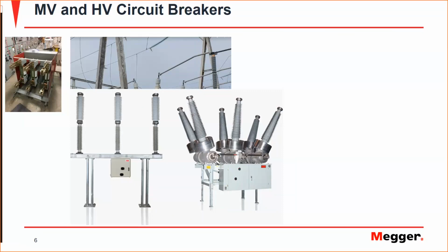The breaker on the left here is a live tank circuit breaker, where the interrupter section of it is live. So any maintenance job for it requires you to do a lot of isolation. Even if you want to clean the circuit breaker, you cannot do that since the body itself is live and has safety hazards.